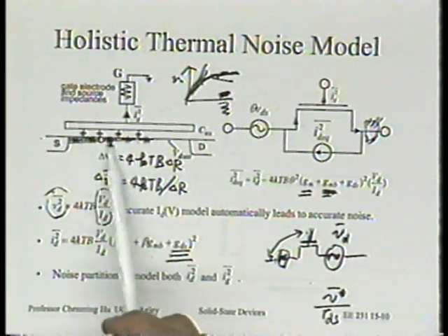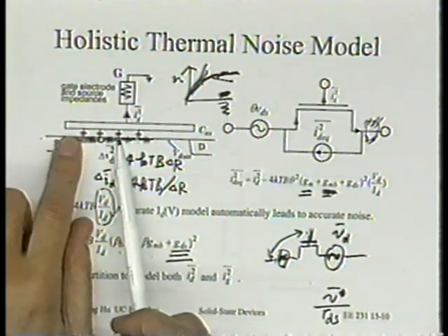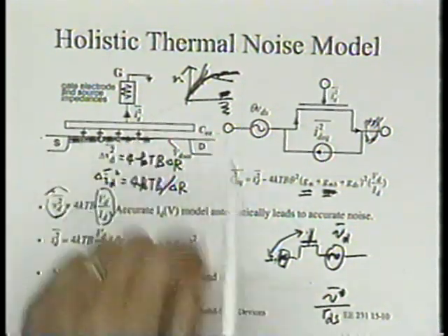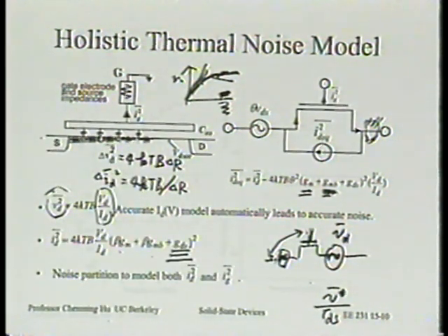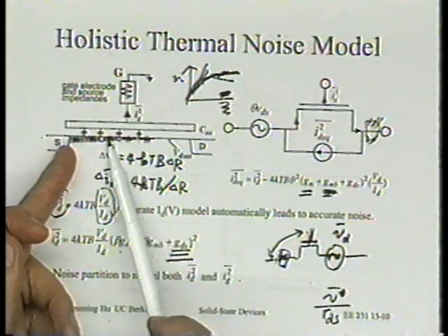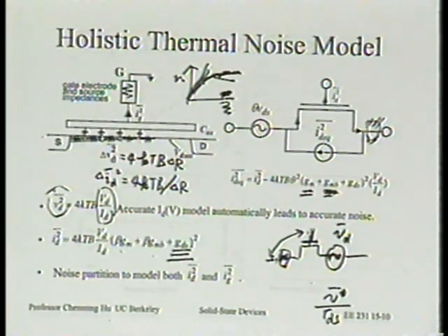In other words, depending on the channel, some of that you expect to be closer to the source, some closer to the drain. So the challenge remaining is to figure out an expression for beta, very similar to the eta we got in the previous equation. You can always figure out what fraction is effectively amplified through the GM and what is not. That fraction is called beta.